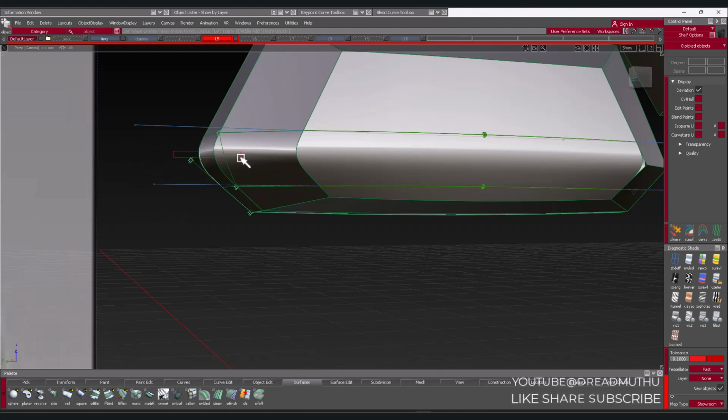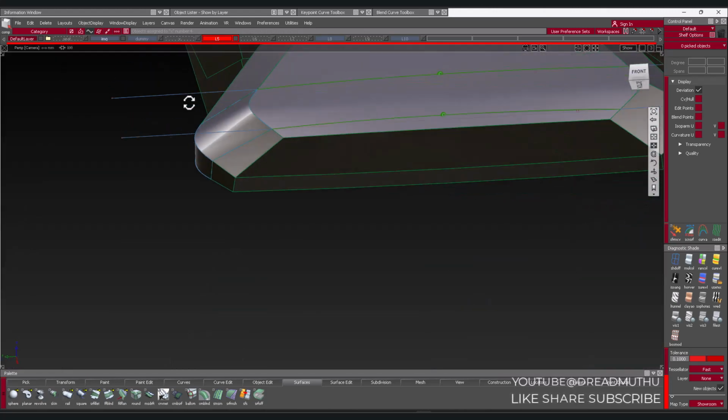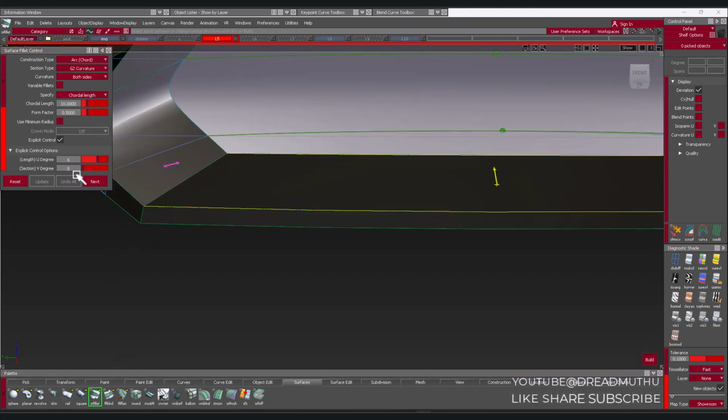Select this object first and we'll delete its history because the curve seems to be messy, so we don't want to do this again. Anyway, so we need to do fillet here. So for that I'll select fillet again. That's too big. 5. Yes, 5 is okay.